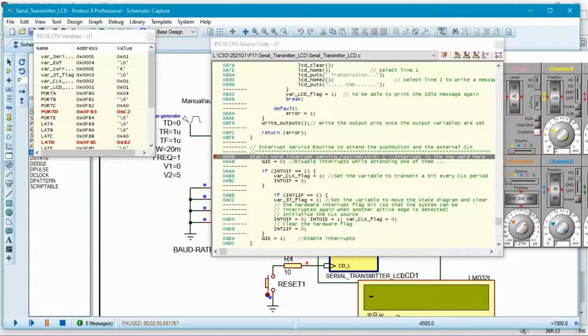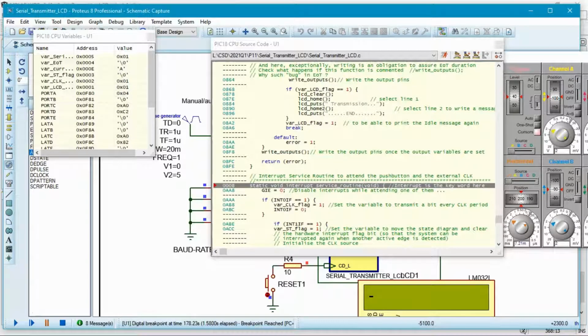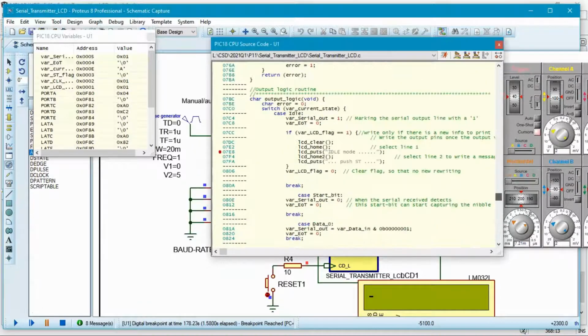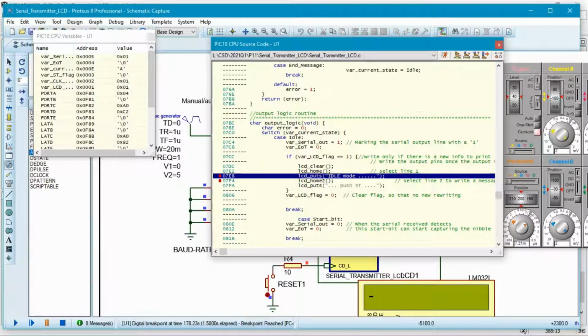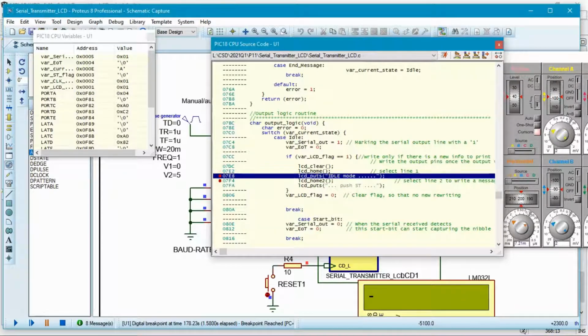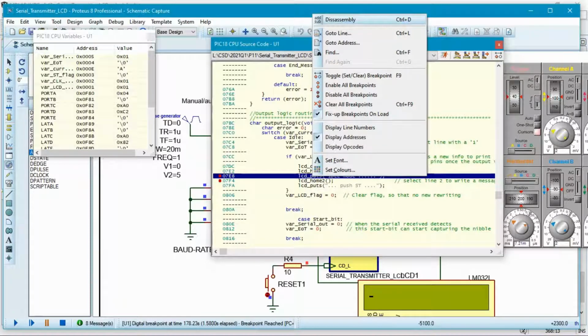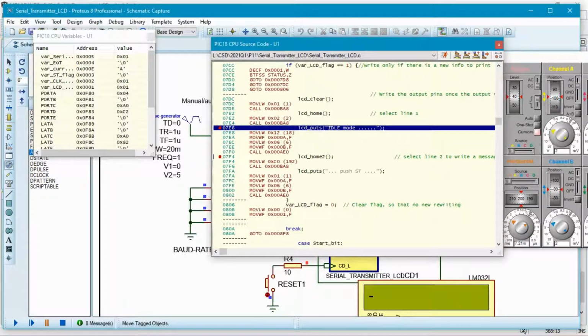This is the interrupt, and now let's run. Let's place the other breakpoint here. So you see, the program will go running and will break here at the beginning of this LCD put string instruction, and will continue working later and stop at the next breakpoint. You are just placing breakpoints for the duration of a single instruction. That looks like C naturally, but remember that this is not that easy. You have a lot of assembly instructions here to execute from one breakpoint to the next.